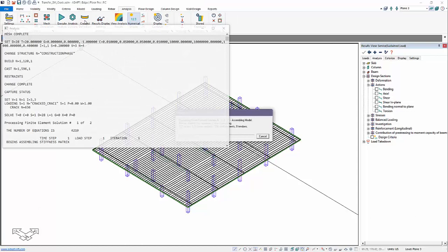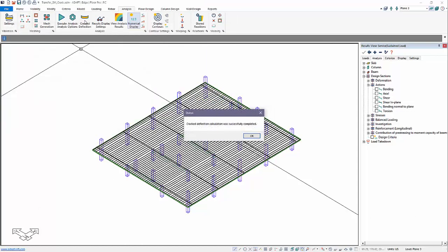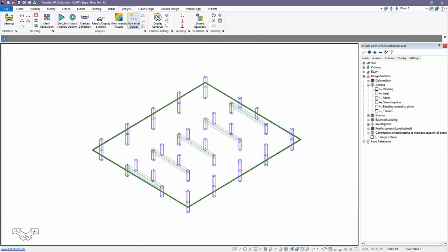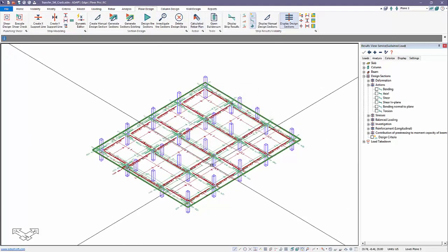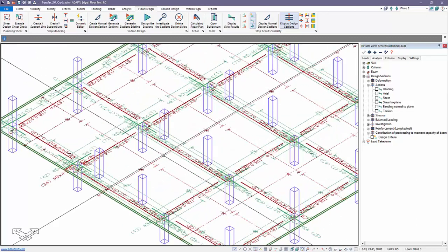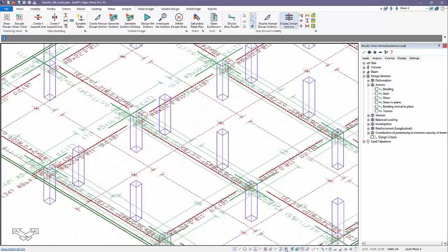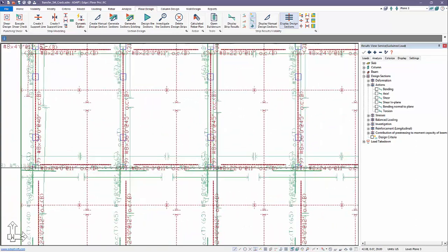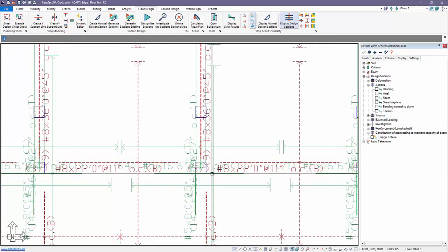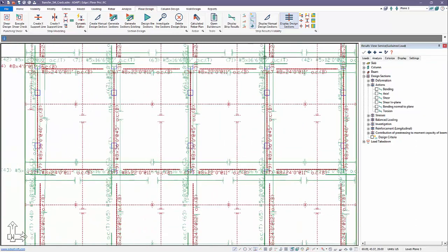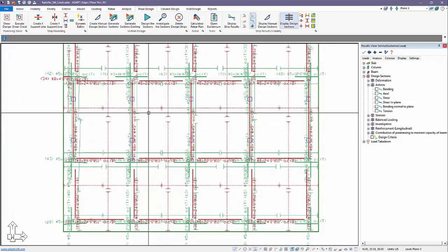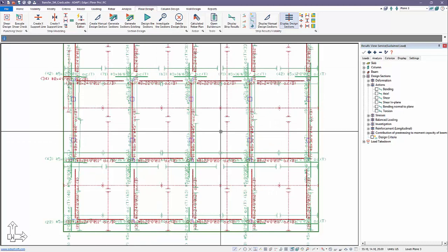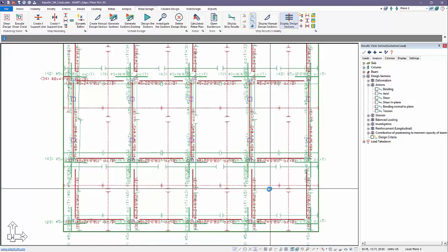And before we proceed into actually looking at the cracking, we're going to go ahead and select the default display, and I'll generate the reinforcement output for this run. And you can see, for example, in these beams, we have roughly 9 number 8 bars. So there's not a lot of reinforcement. These are currently being designed as RC. Relatively speaking, there's a lot less reinforcement in this run than what I'll show you here in just a moment.